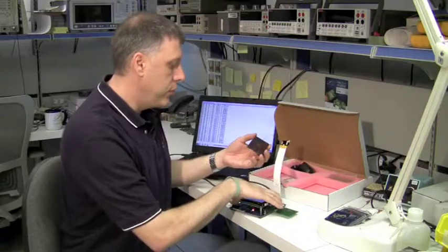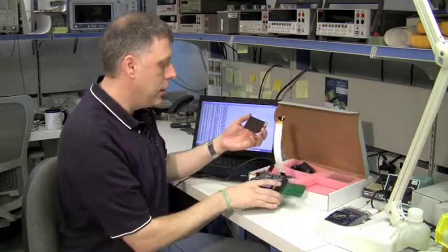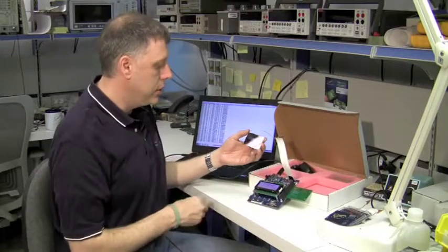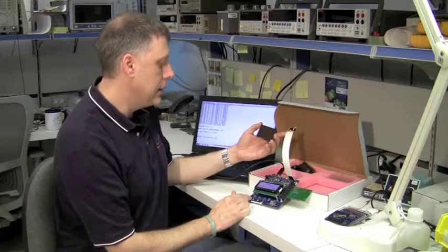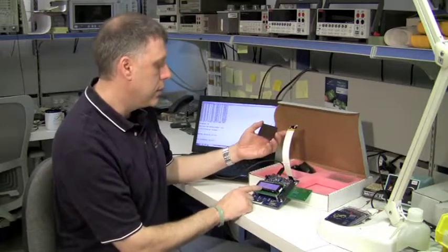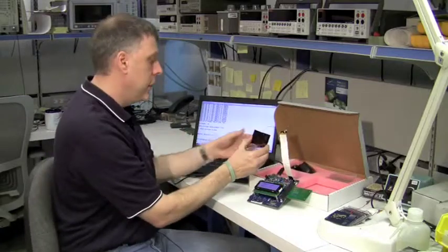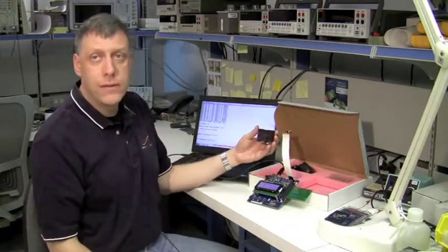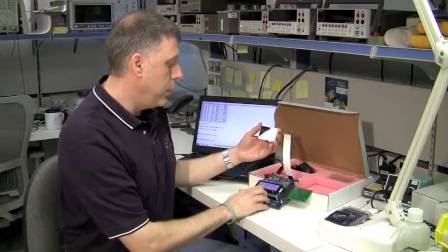So I have to move a switch on my ADP kit to enable the energy harvesting header, and then if I reset the board, what we're going to see is it's going to detect this energy harvesting cable is connected. Runs through quick calibration. So this is EH interface active, and it even displays it here over the serial data log. So now I know that my energy harvester has been connected and recognized. So what I'll do is put it into pass-through mode.